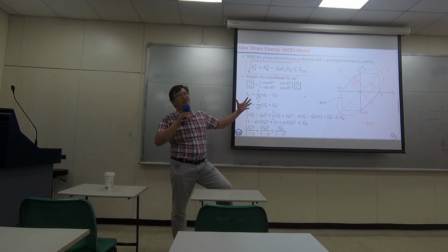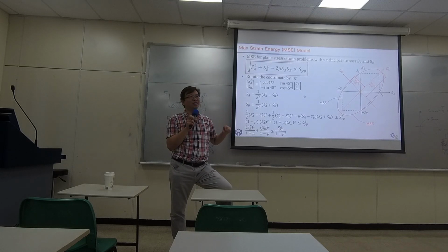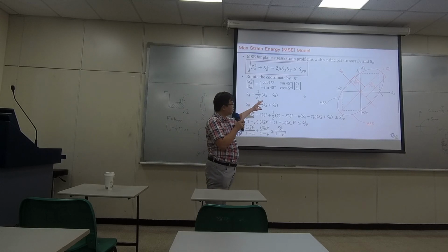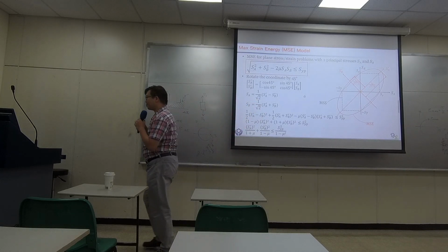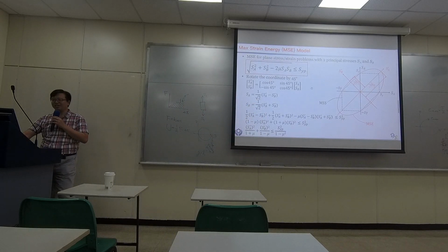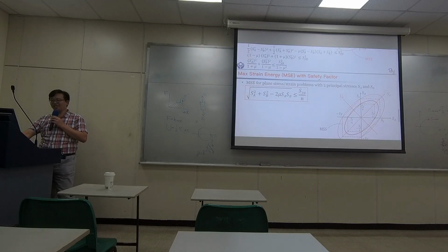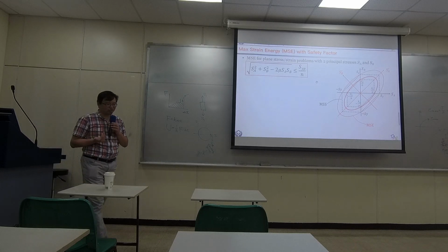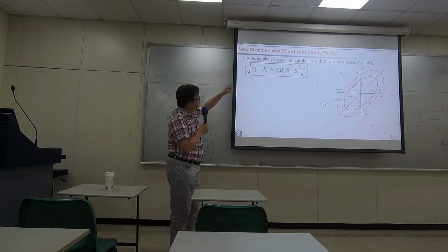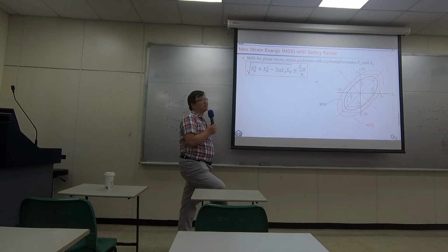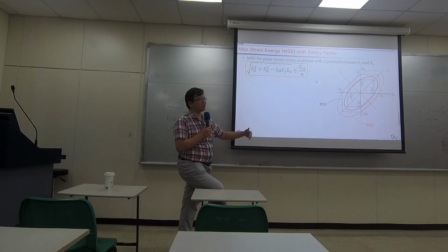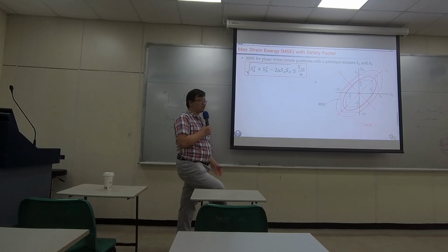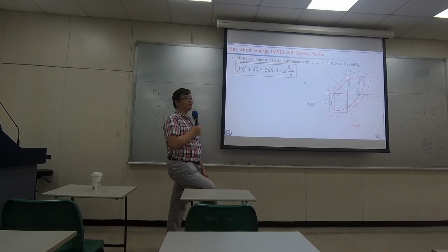In the real world, there is so much uncertainty. Those are uncertain numbers, so we need to apply a safety factor. We allow those noises and issues to be avoided by the trick of safety factor. So we don't push ourselves to the very limit, because your material could fail.